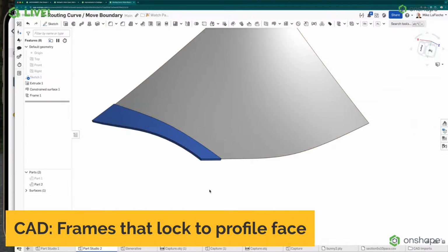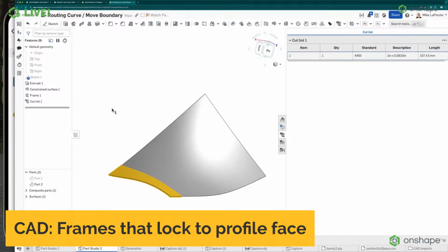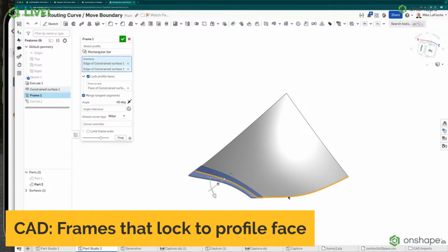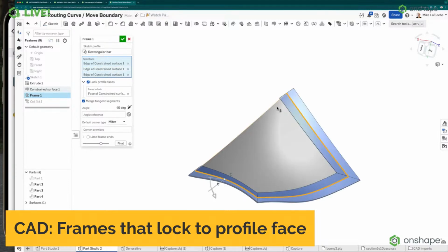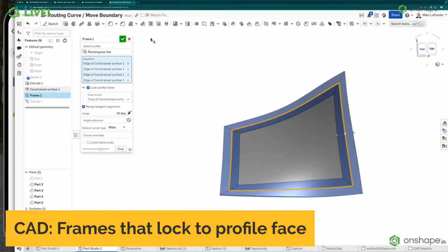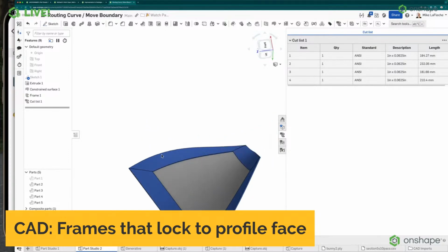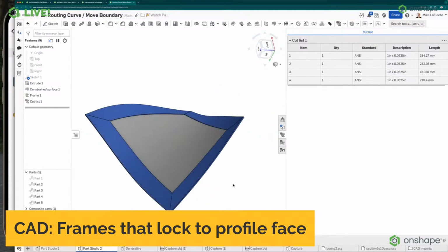We look at our cut list for this as well. It should auto calculate it. Let's see what happens. Select all frames. Oh yeah, there it is, 157.43 for the length of material on that particular frame. And if I keep on going, obviously you'd have to. Actually, that's looking pretty good. I mean, this is getting to the point now where you could have very, very interesting shapes now for your frames, based on any kind of reference input.